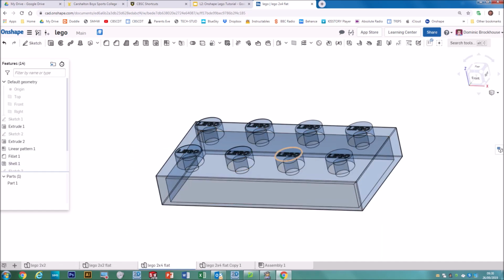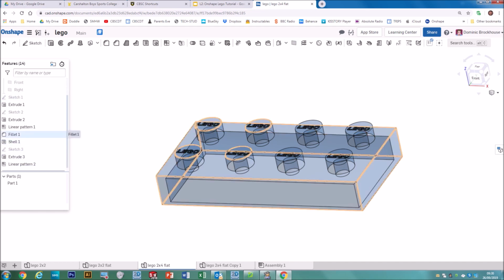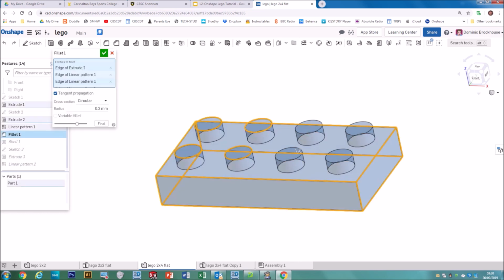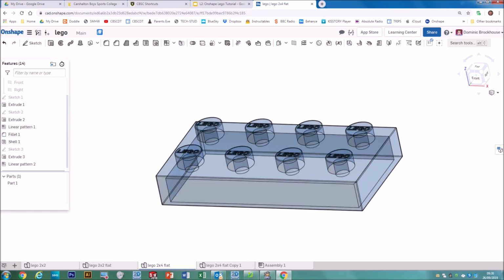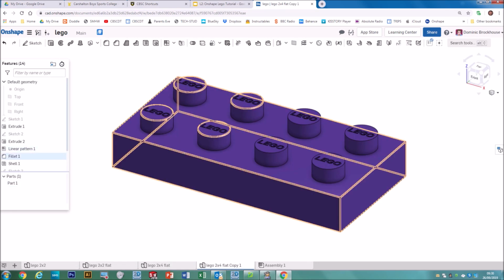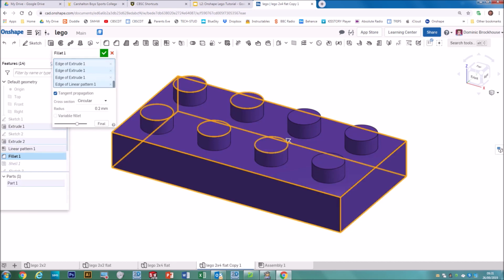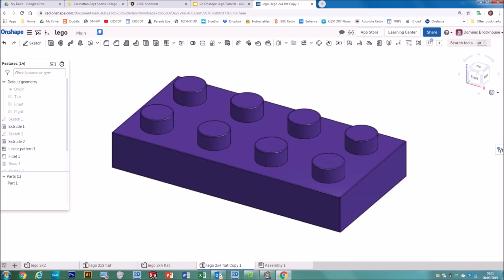So where I've got some fillets missing, let's look at our fillets there. So it's filleted those ones, so right click, edit, and you can see the ones that it's done and the ones that it hasn't. So if we just go in and click on the 4 dimples, the new dimples that we haven't filleted, then it will add them to the list, and that's done. Alright, so I'll have to do that on here as well. Go to the fillet, right click, edit, and we'll just add those top surfaces of those 4 dimples to the list of items to be filleted.